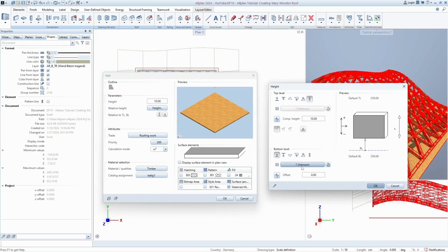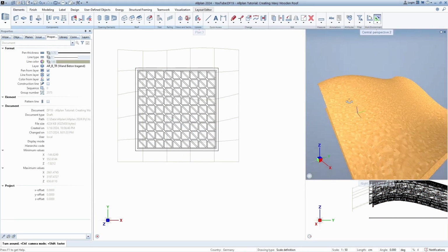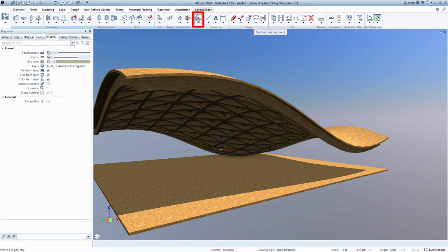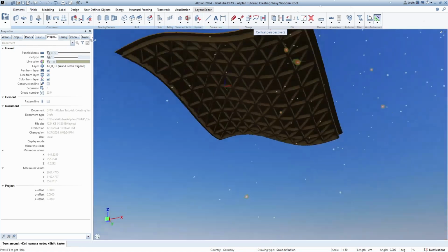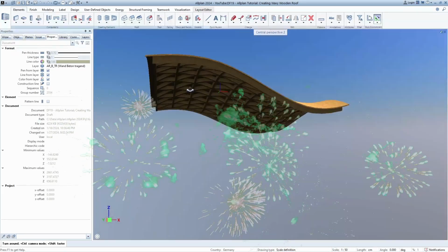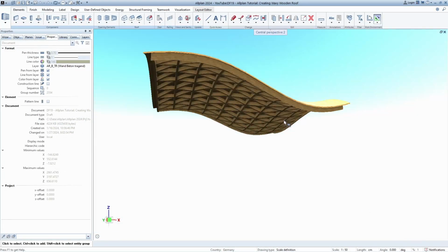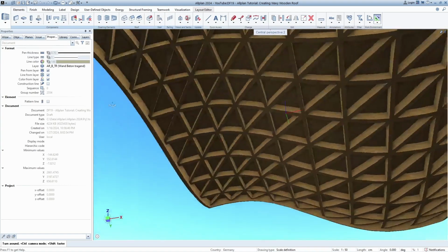Now let's attach our plate to the roof, and if Allplan shows you two plates as well, just run the update tool, then all, and Allplan will refresh all views and the entire model. Well, congratulations, the roof is finished, only facade remains. I promise it's not going to be that complicated.